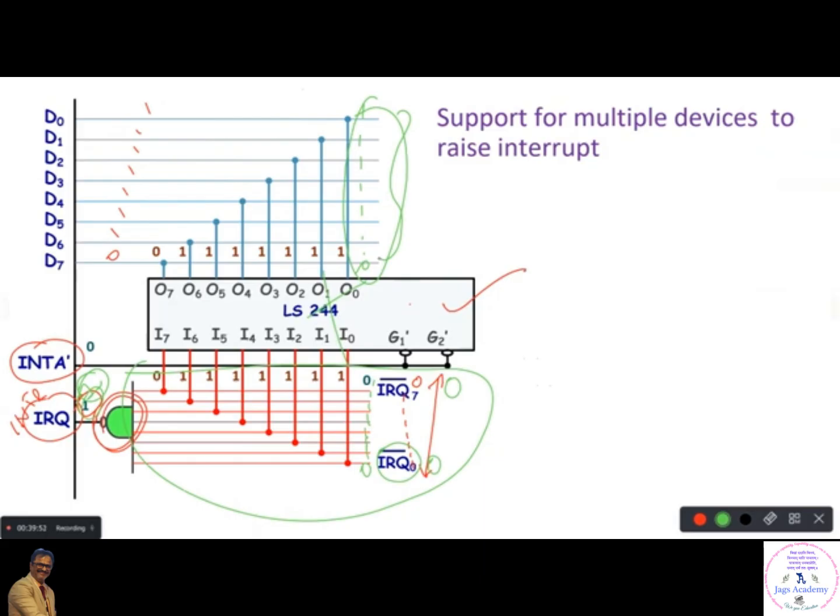I've understood this. Okay. So at present, this setup can serve only one interrupt request. There's no setup to give priority here. So this is the circuit which is used to load which interrupt has actually interrupted the microprocessor. I've understood this circuit now. The circuit is very important. You will be asked to design the same circuit for different interrupt vector numbers. We'll see that.